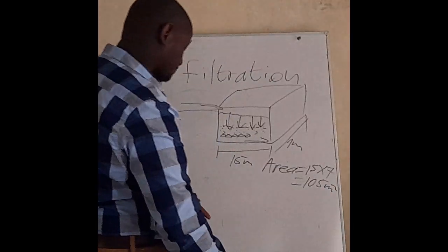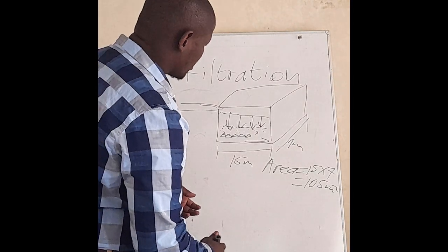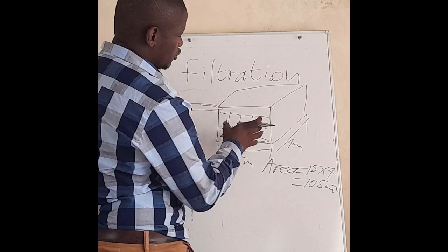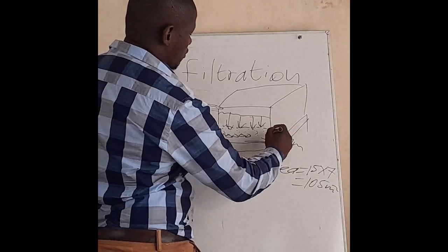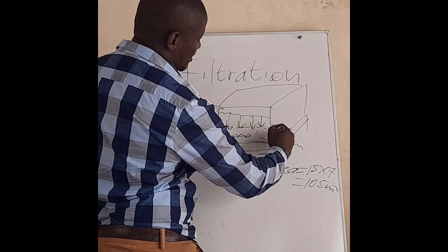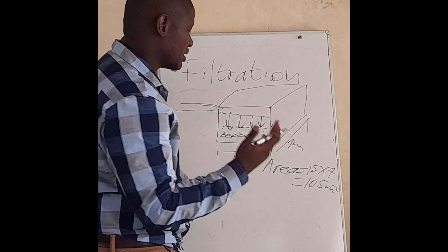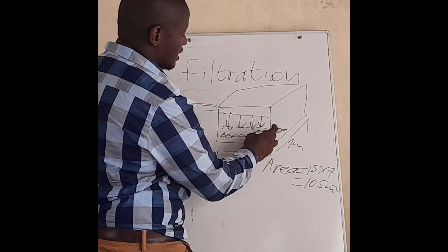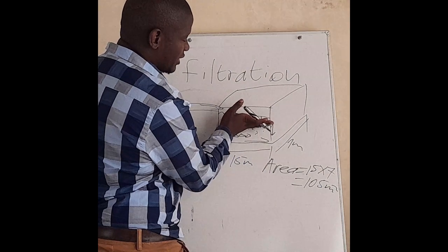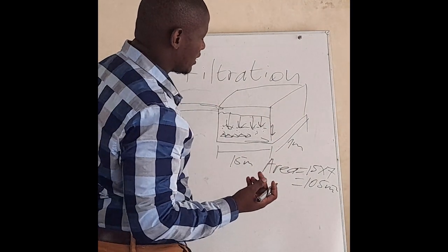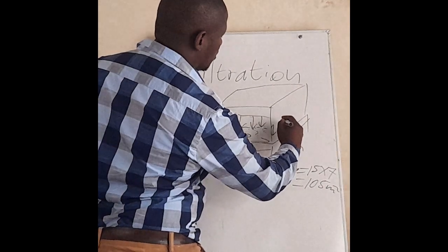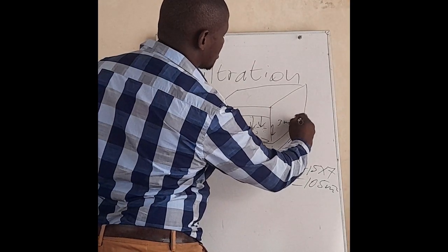meters squared. Then our next step is to also get, in most cases we'd normally be given the flow rate, but really it's more like the velocity, but nonetheless you need to get the flow at which the water is penetrating or filtering through. Let's say it's filtering at a rate of 3 meters per hour.